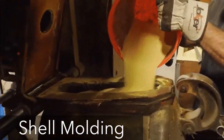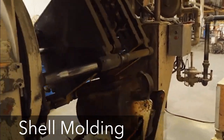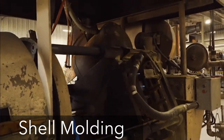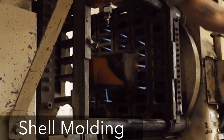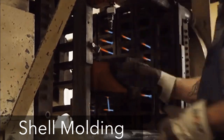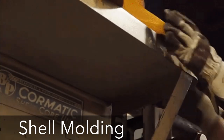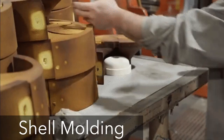The assembly is then placed in an oven for a short period of time to complete the curing of the resin. In most shell molding machines, the oven consists of a metal box with gas-fired burners that swing over the shell mold to cure it. The shell hardens around the pattern and is then removed from the pattern using built-in ejector pins.